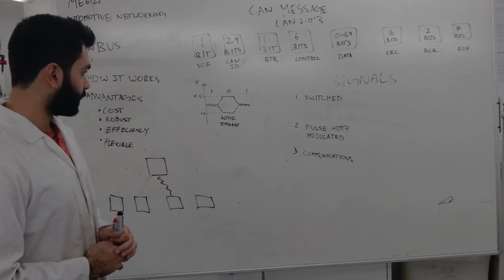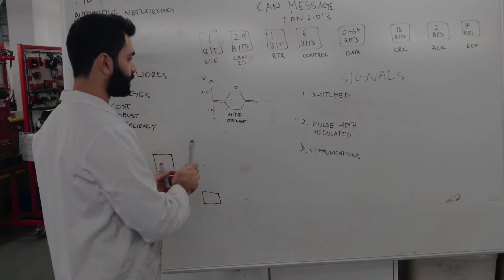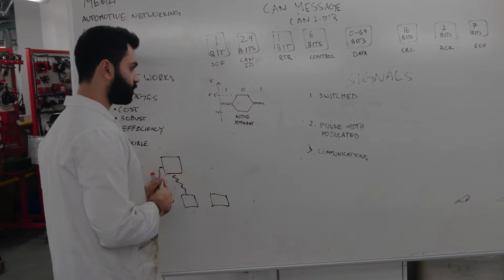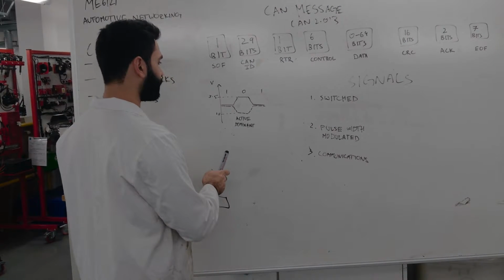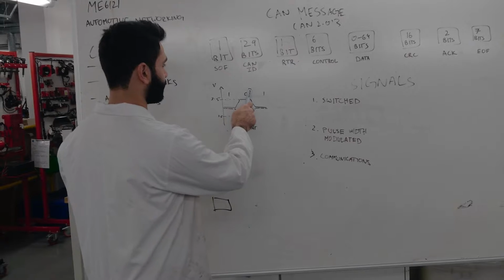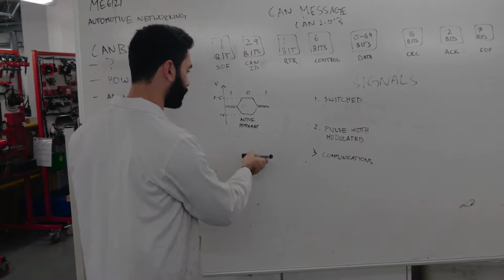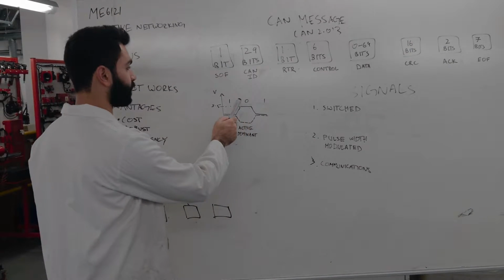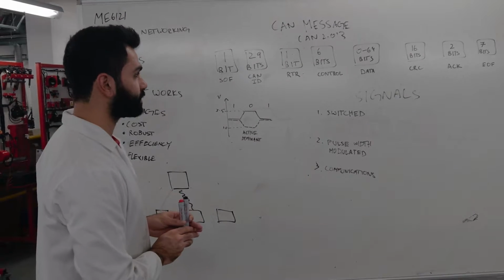Important thing to know is our CAN signal, they're usually represented like that, with voltage from 1.5 to 3.5. The message is usually mirrored with the high voltage being the dominant part of the message, identified as a 0 rather than 1, which is the inactive part of the message.